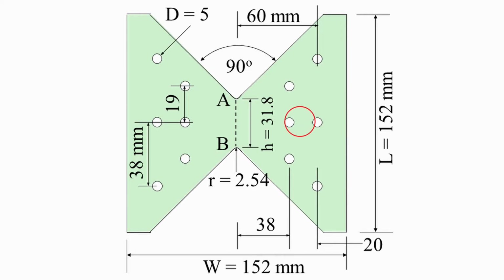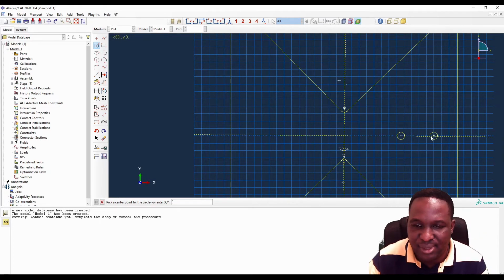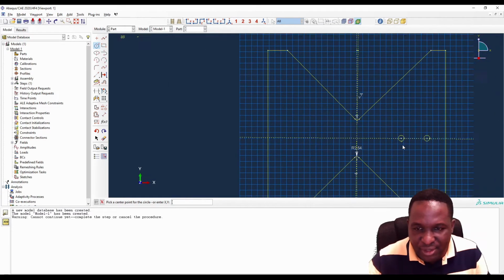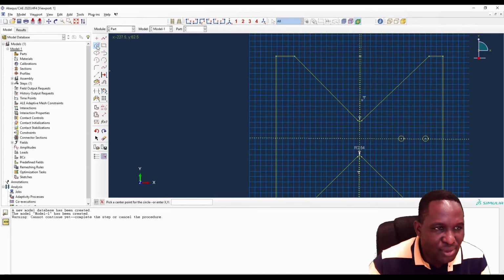The next circle we know is going to be a distance of 60 from the center line. So 60 and 0 and 62.5 and 0 will give us those two circles. All right. So the other thing that we know is that in the vertical direction, the first circle is 90 meters up and 90 meters down. So what do we do? So we click on that circle.